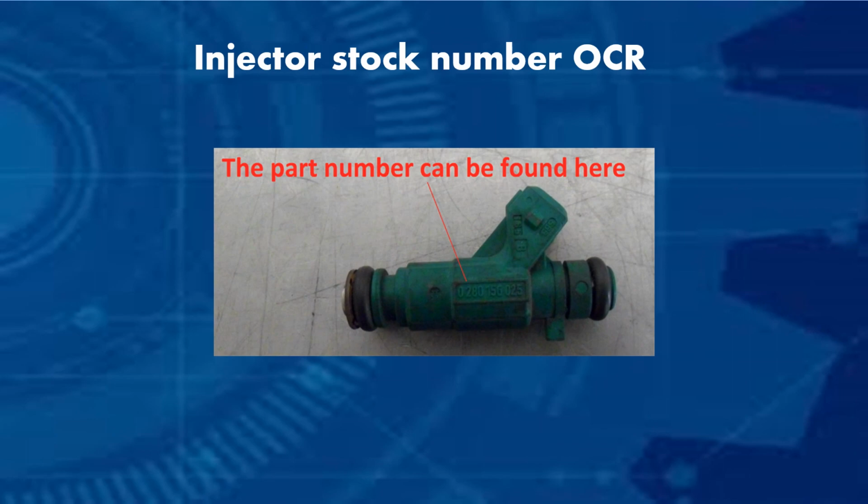The purpose of the fuel injection system is to deliver fuel into the engine cylinder, while precisely controlling the injection timing, fuel atomization, and other parameters. Fuel injectors are sized by their flow rate. Flow rate is a measurement of how much fuel can be delivered over time. It is listed in pounds per hour or cubic centimeters per minute. The right size injector can supply enough fuel under full load condition at an 80% duty cycle.